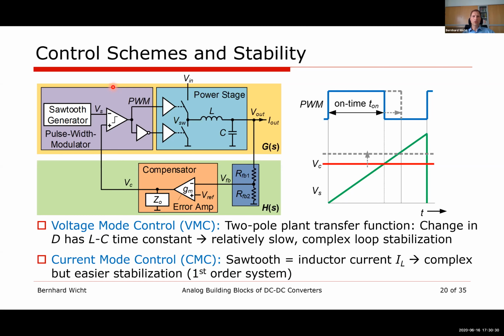Yeah, of course, it's not shown here, but we always need to have a capacitor at the input and as close as possible to the power stage, because we talked about, there was this question on the parasitics. The longer the distance, the more L we add here. And we see, of course, current spikes within here. So that causes little voltage spikes, and that's visible in the EMC spectrum.